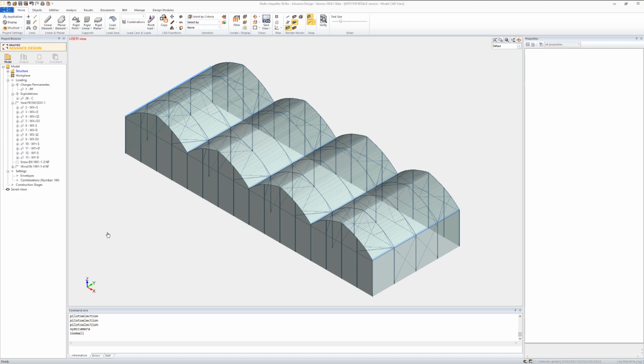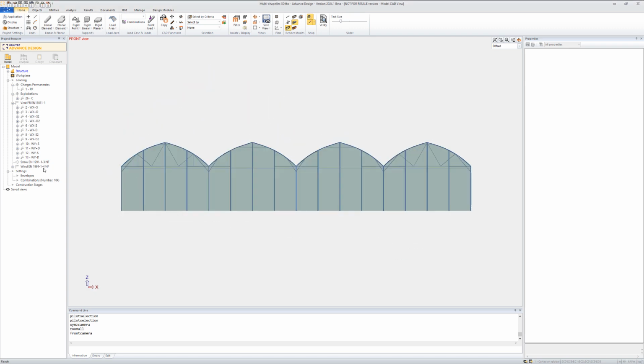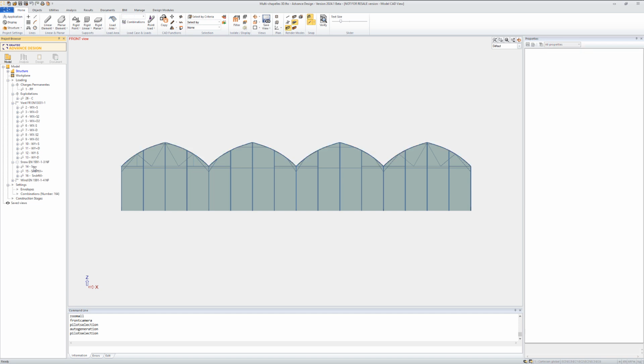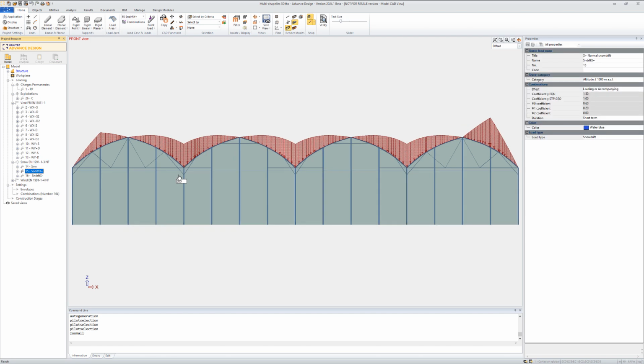Alright, so now let's generate snow forces on this building, which is made of multiple vaulted roofs. Snow generation again is instant. We get the expected snow cases, starting with the undrifted snow arrangement. And then we've got the drifted snow, where we can see that on the first and last half roofs, we see the two peaks from before, the one being 50% lower than the other, and on the inner base we can see that the snow force gets stronger due to the accumulation that we have on the middle volumes, so here, here and there.